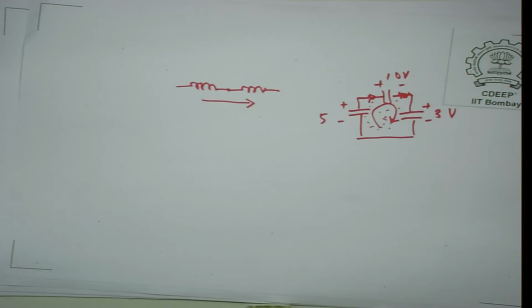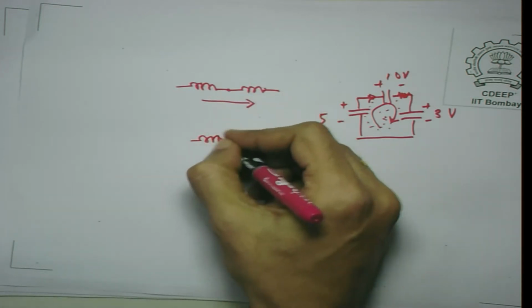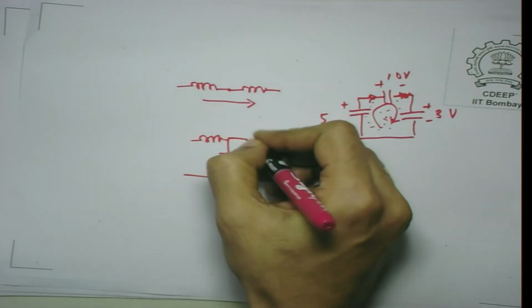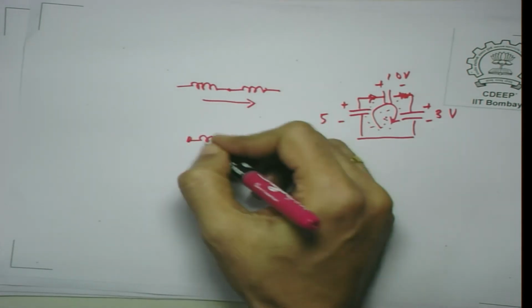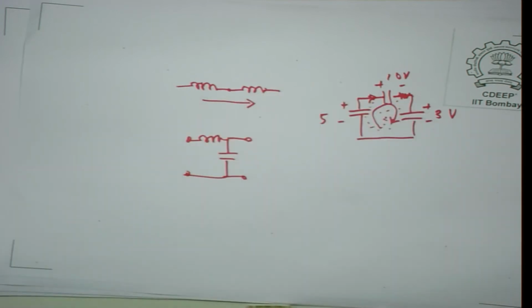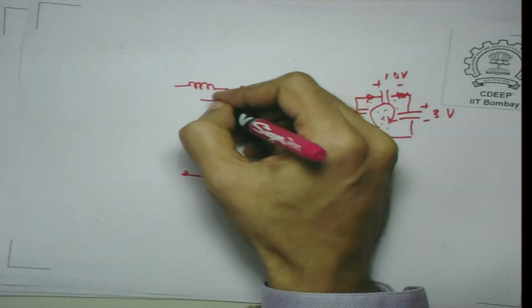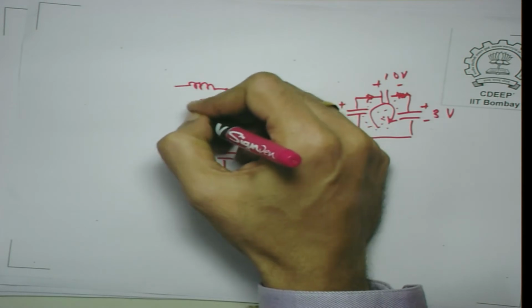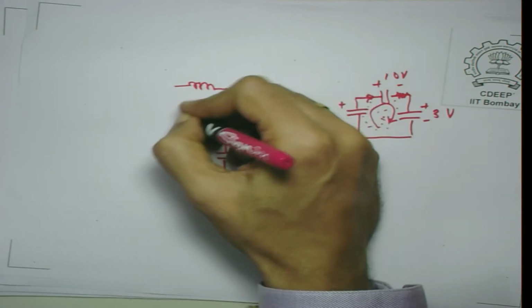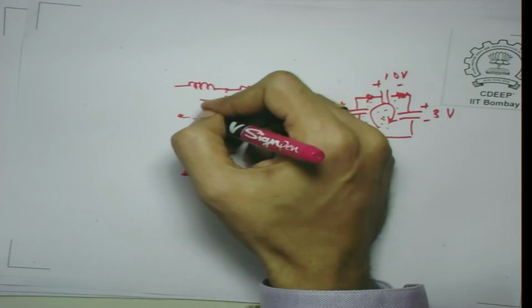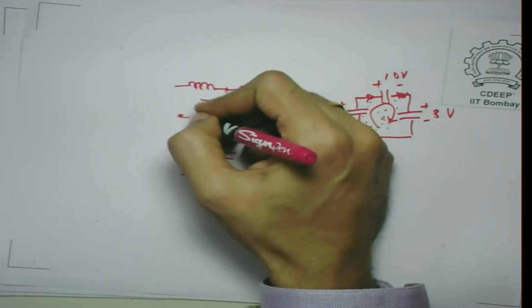An interesting thing of course is, if you have a circuit like this, it is easy to choose the states, because here the inductor current and the capacitor voltage are independent states. I have used the word states, or rather I should say that I can independently specify initial conditions here, whereas here you cannot. Again, in real life you may be saved by the fact that in any metallic wire, if some charge buildup occurs, then there is an electric field and there will be a voltage drop.